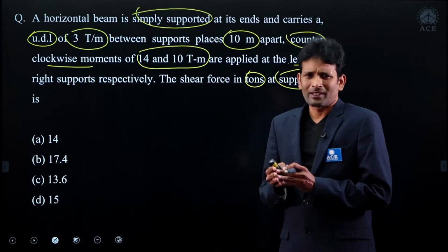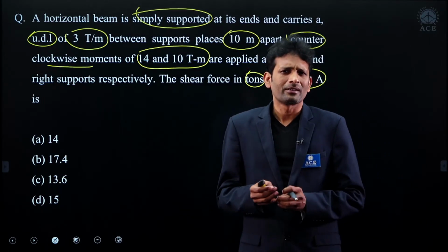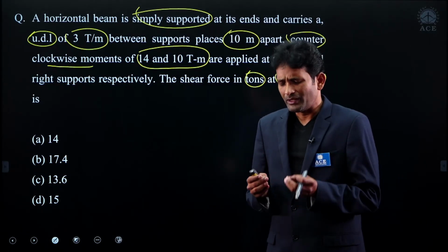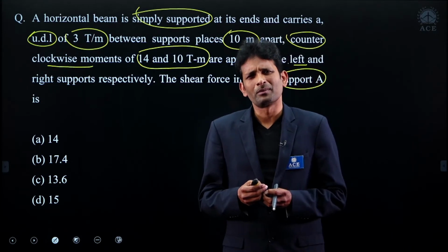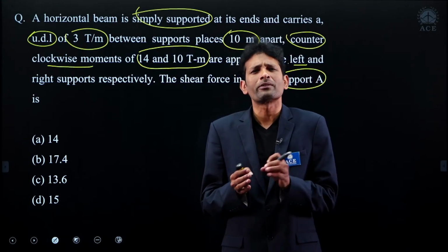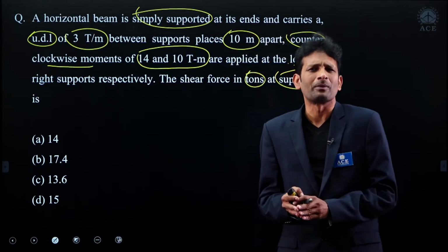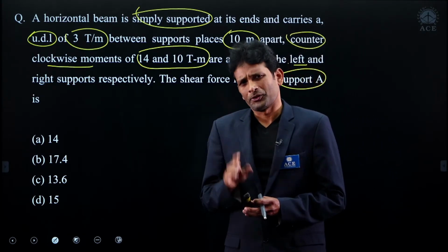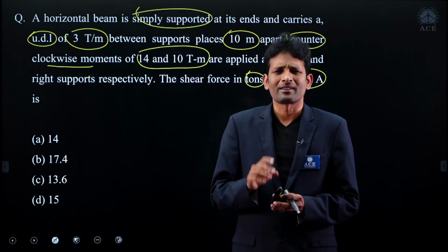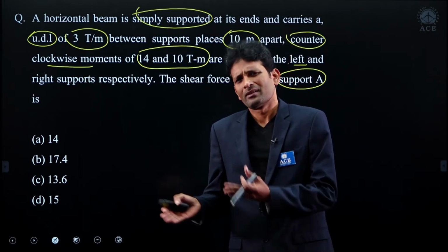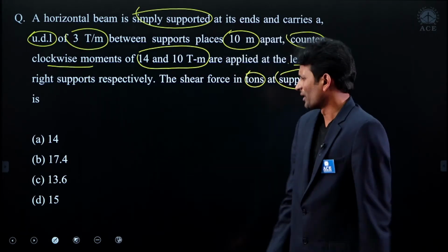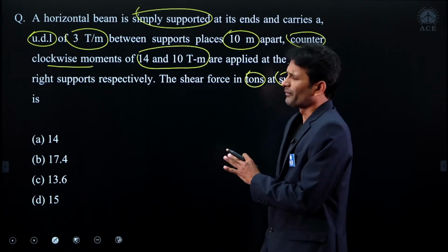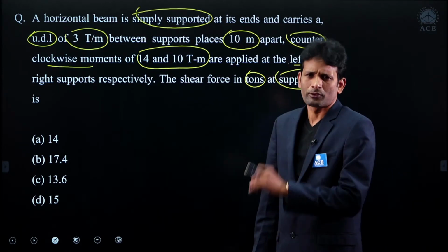See, most of the times, as I told you before, not only in SFD and BMD but also when finding out deformations, I said that most of the times the principle of superposition is the predominant principle in strength of material. If possible, try to apply that principle by using the standard cases. Otherwise, as usual, the same traditional approach you can take. So I can take this problem first by using the principle of superposition.